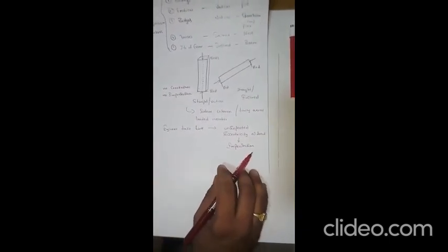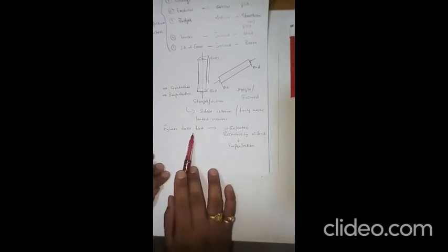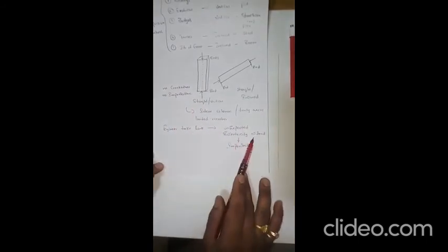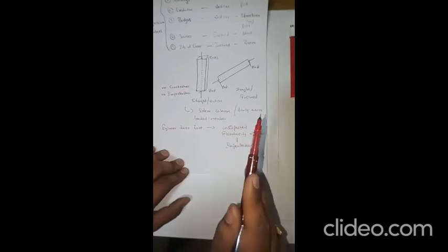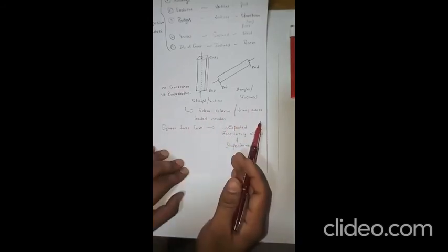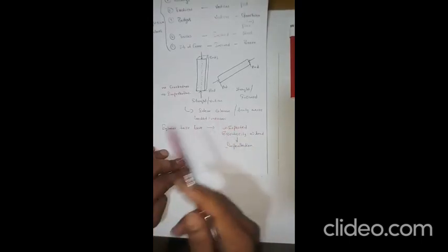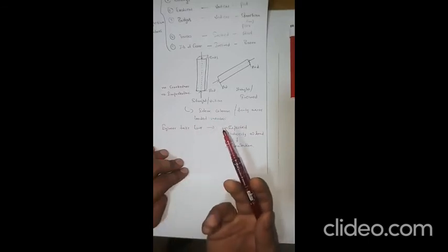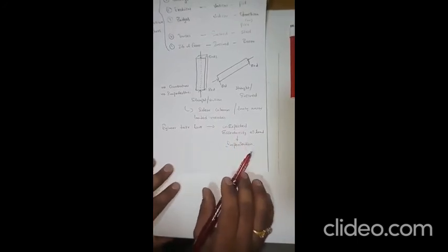When a designer designs a section, he always designs a member to transfer load vertically through its axis. But practically, in engineering practice, unexpected eccentricity falls in the load. Why? Because your column should carry a beam load, isn't it? When the beams are placed longitudinally, that force will transfer to the column with some eccentricity, isn't it? In that eccentricity, definitely there is a chance of eccentric load, which makes the member have buckling characteristics, a lateral buckling. So unexpected eccentricity of load may happen, which makes the member imperfect.